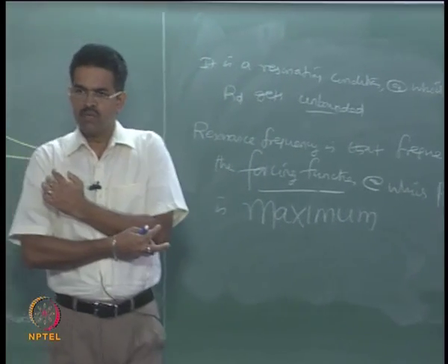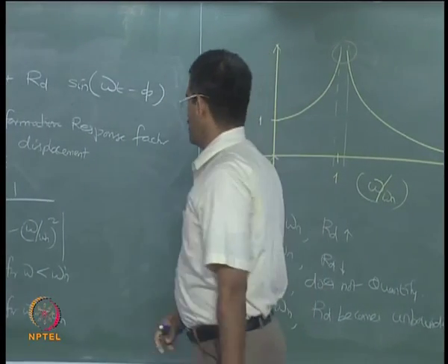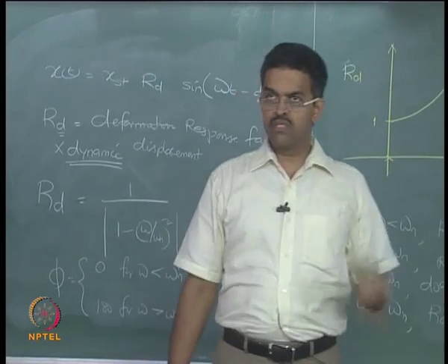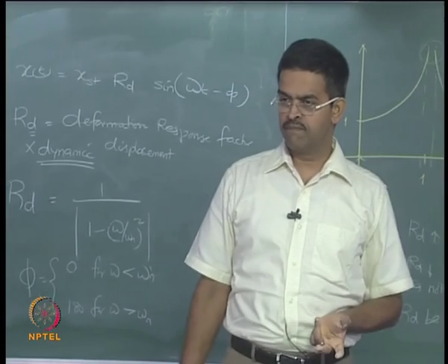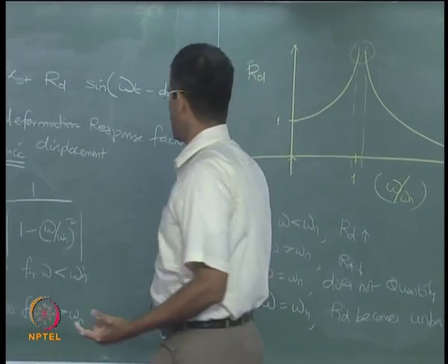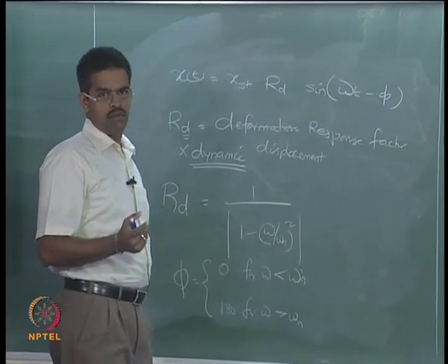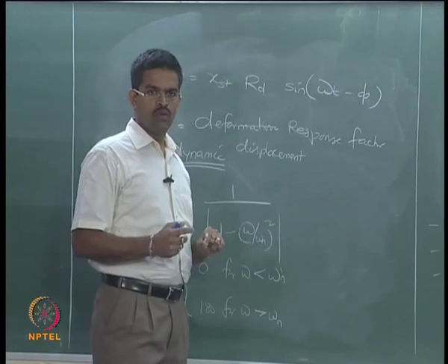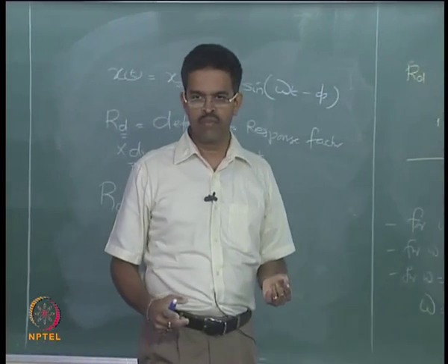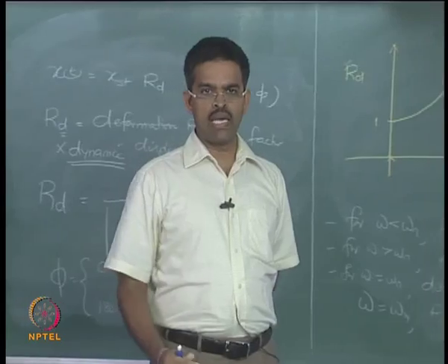So, in a given plot, if you are able to find out a specific value at which the response factor gets its maximum amplitude, it is that frequency of the forcing function which is called resonance frequency. Mathematically, it is very simple: there are two variables, I can fix one and vary the other with respect to the fixed value. What is fixed in the discussion is omega n, it is not omega. That is what I mean by this statement. I am fixing omega n and not omega.